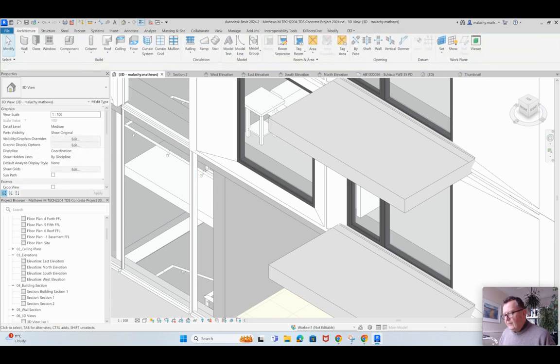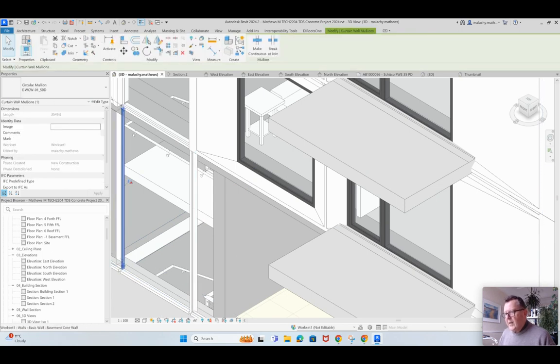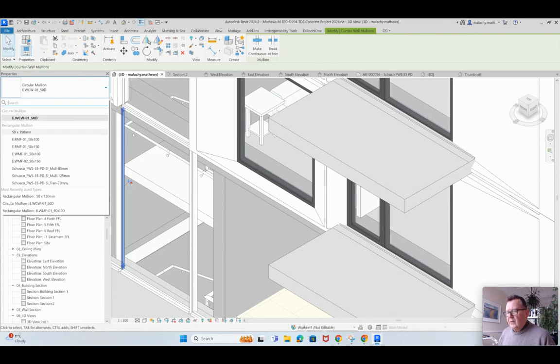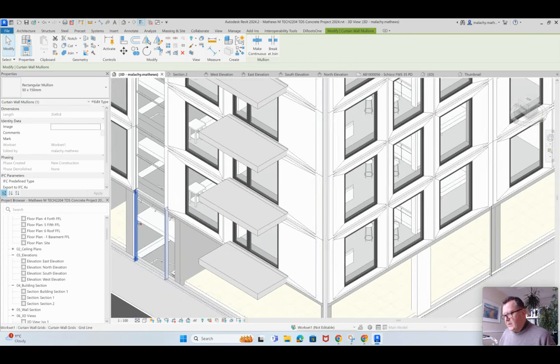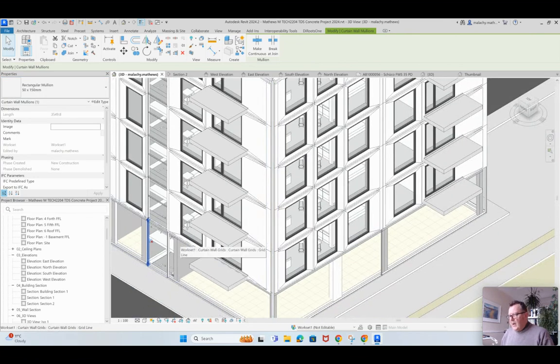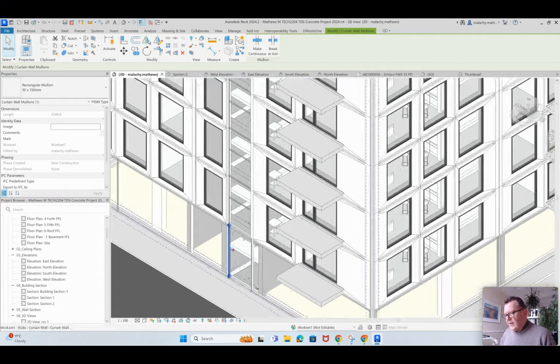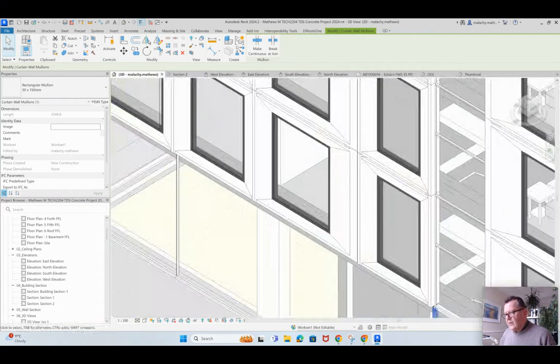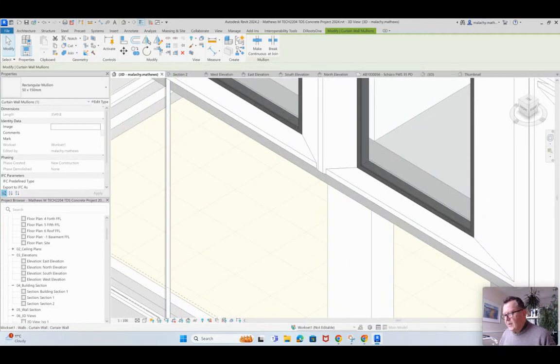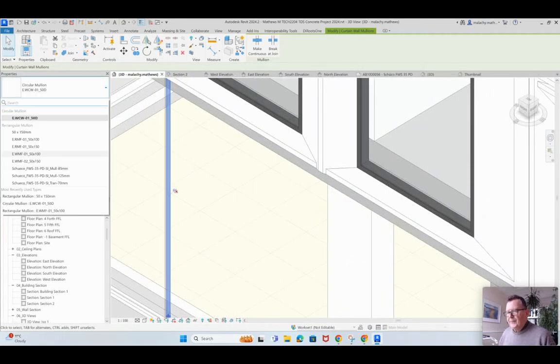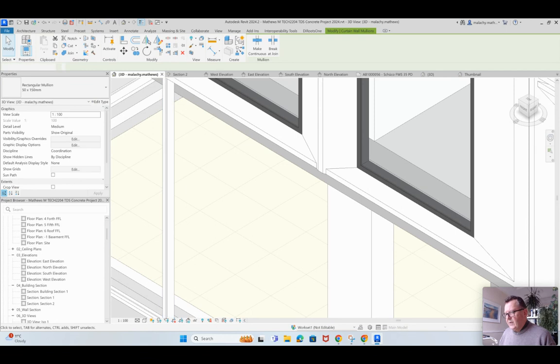Now we'll come over. We can do that again here. Unpin. I'll swap out that one there. Now I'm going to take a look at the south elevation. I think that occurs once more over here. It does. So again, same thing: get in, select, unpin, and 1 is to 50.